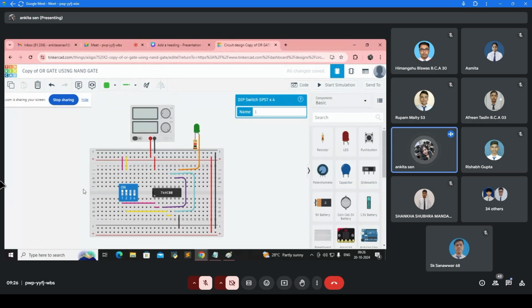Suppose you have a requirement of four switches. If you use a slide switch, then you require a total of 12 connections, correct? So there will be a lot of wire requirement and space requirement, which will be very messy. But in case of this switch, the wire requirement is less, the space requirement is less, and the connection is also very easy. To make it understandable, I have used a circuit made in the previous year, so that things will be easily understandable.